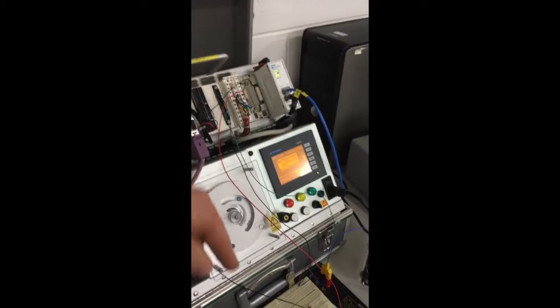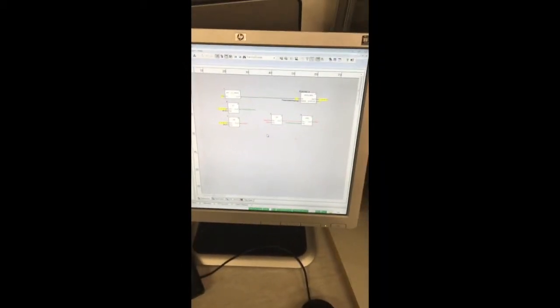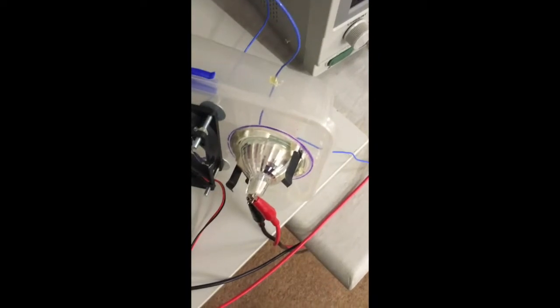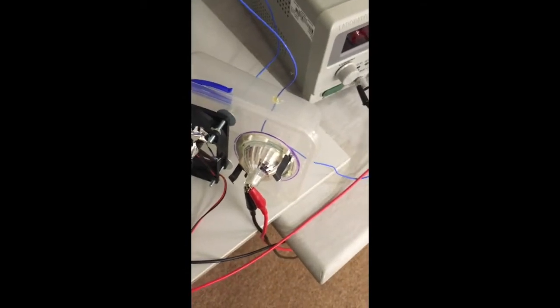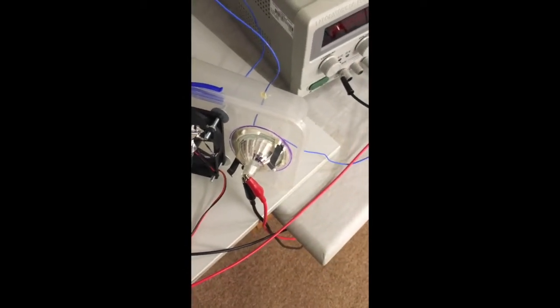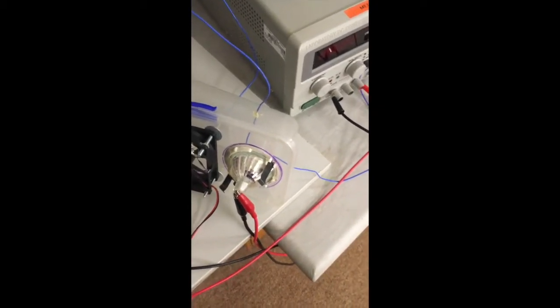Now I did want to have this halogen globe running from another relay module, input and output, to be controlled in a sense that you could increase the temperature and turn it off. But this is a 50 watt halogen globe with a 12 volt input, and it required far more current than I had any resistors to build a buck circuit to control that. So we're manually switching the sun simulation on and off at the power supply, like so.